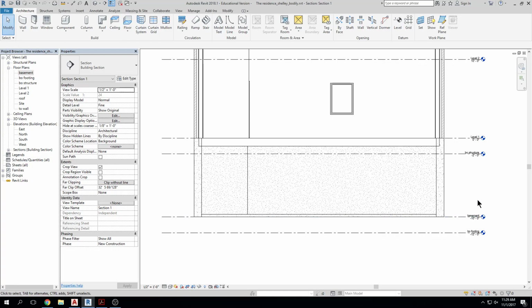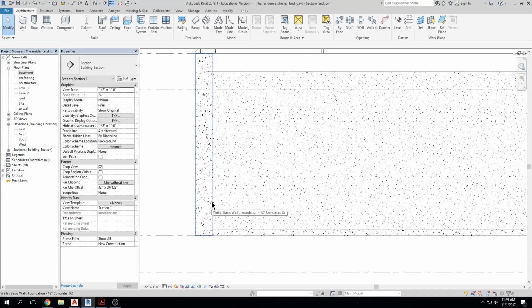Okay, so we're going to create some footing walls here. Again, the structural engineer is going to be key in helping you generate your footings, right? What thickness they are and what height they are. You can have a 10, 12, whatever. Some footings are really large, some are really small, but we can have a 10-inch thick footing, and then maybe we have it 24 inches wide or whatever, right? But you'll work with your structural engineer to determine what your footing size is, okay?